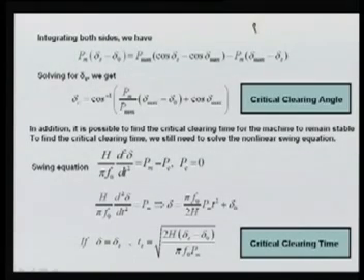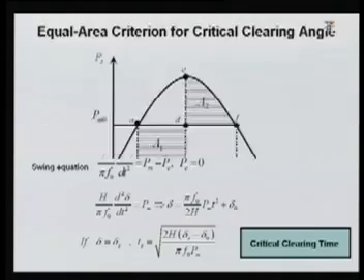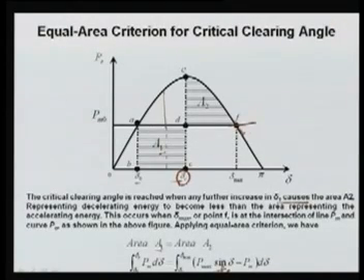Here we know PM is Pmax sin delta max. If you solve this, knowing PM as well as Pmax, you will get two values of delta max. Means in the previous case, if you write this equation, PM at this point F is Pmax sin delta.